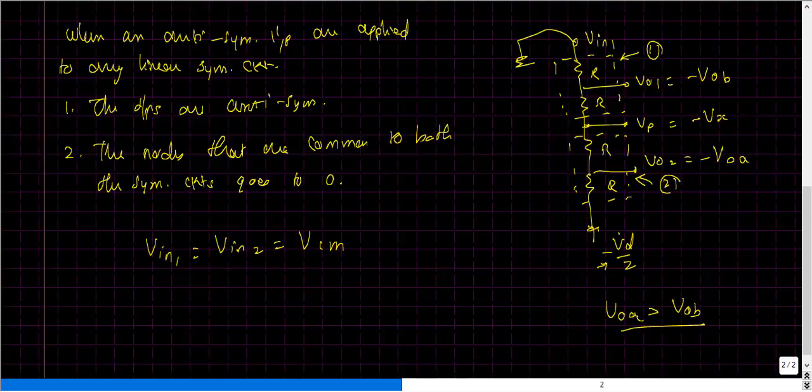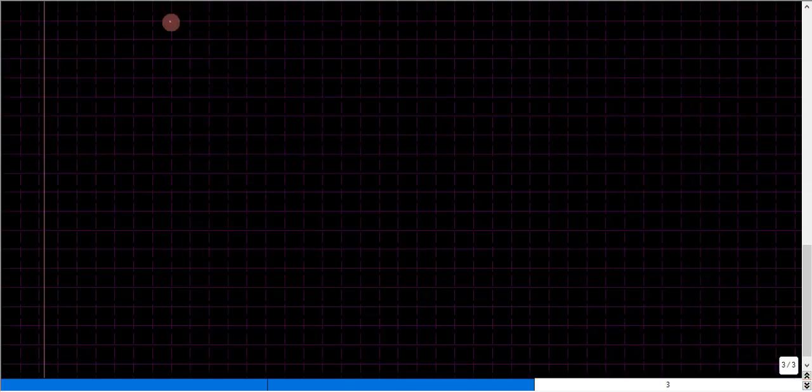I'm going to bring back this same table onto my next page by writing down Vin1, Vin2, VO1, VO2 and the node voltage VP, and there are two conditions here. Again I'm going to apply the superposition theorem, which means I apply each of these values one at a time, whereas the other input is shorted to the ground.